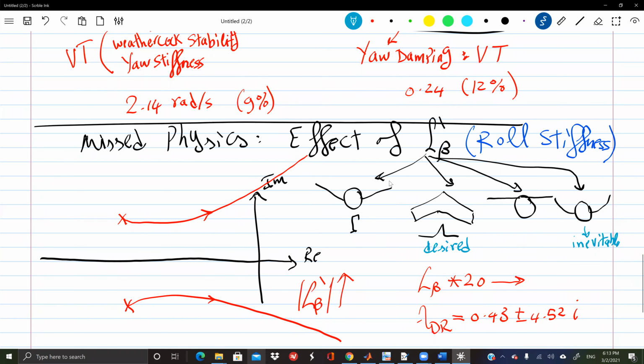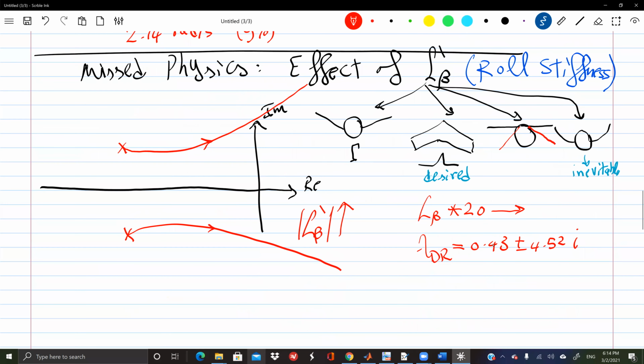So now, this is the only thing, the dihedral, the setting angle of the dihedral, that you have control over. So this is why, for some design configurations, if we have a high wing in addition to these two, then this is too much. This is too much of an L beta, to the extent that we actually use anhedral in this case. We typically see this picture. If the wing is high, then we do anhedral, okay? The opposite of dihedral, to decrease the effect of L beta from all these factors, not to mess up the Dutch roll. Any question about that?